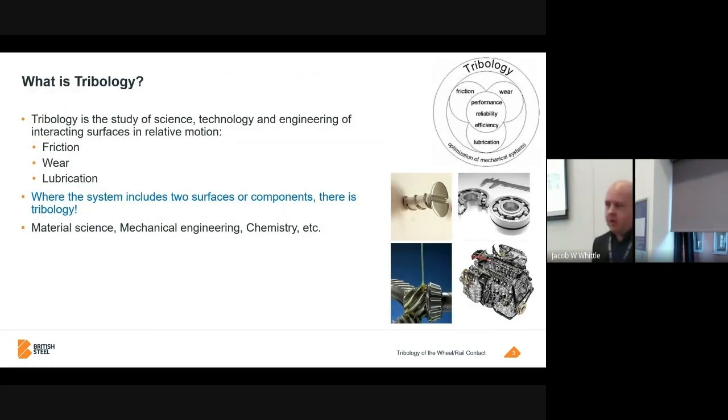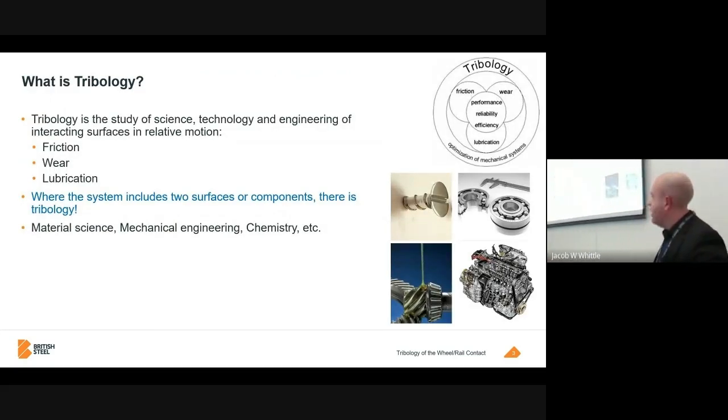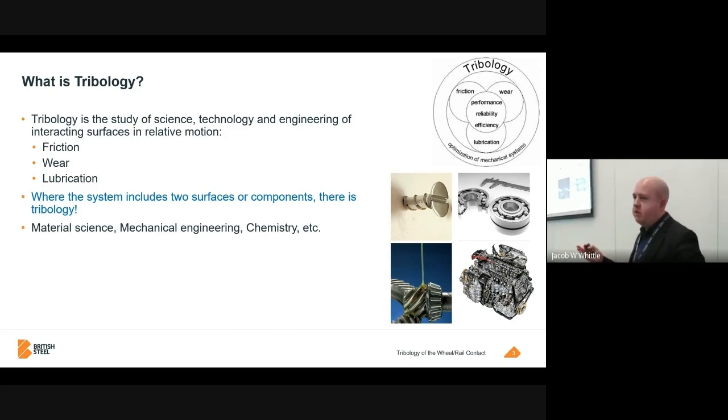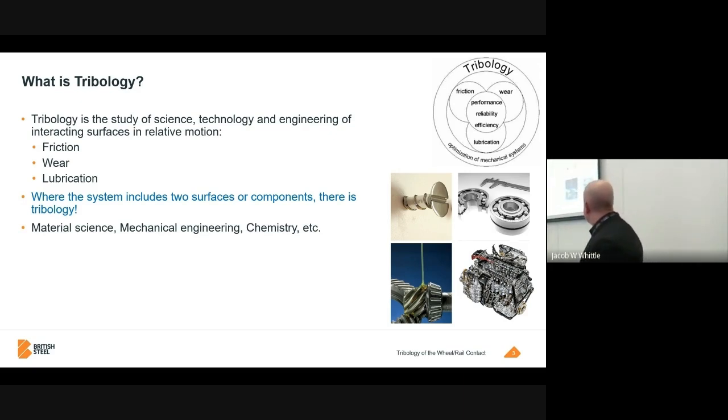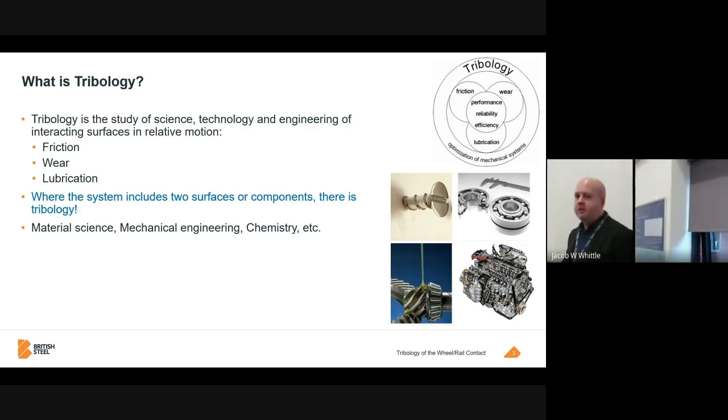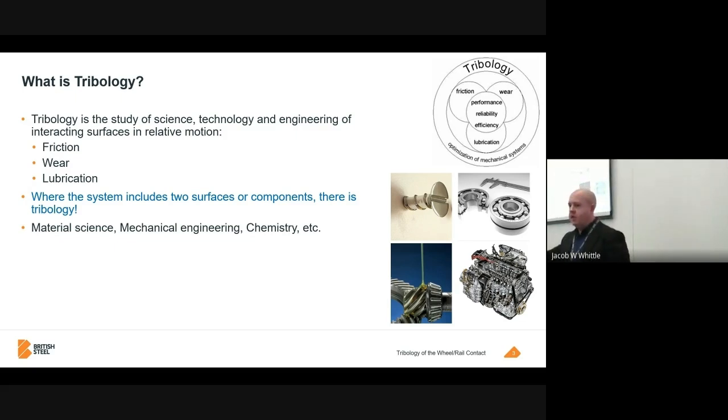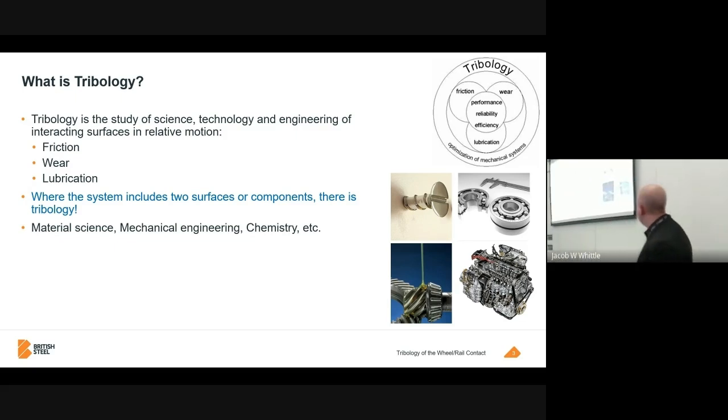So what is tribology? Tribology is everywhere. It's in everything that we do. It's the science and study of interacting surfaces in relative motion. It incorporates friction, wear, and lubrication. And you can see a few examples. Just a basic screw in the wall. That is functioning because of tribology. That friction is holding it torsionally into the wall.